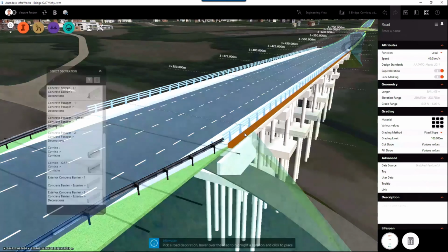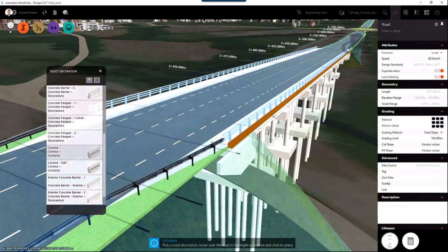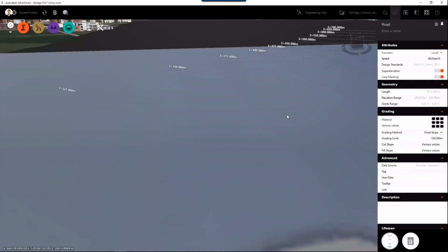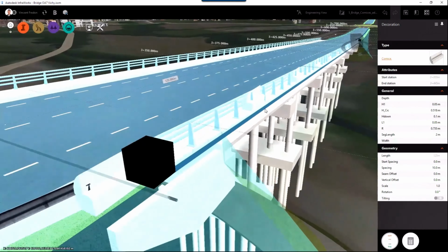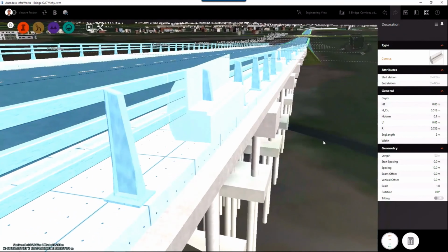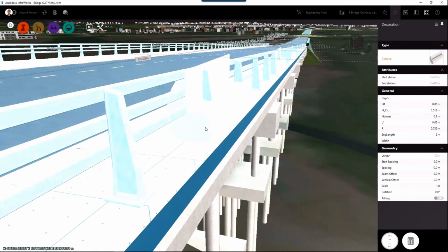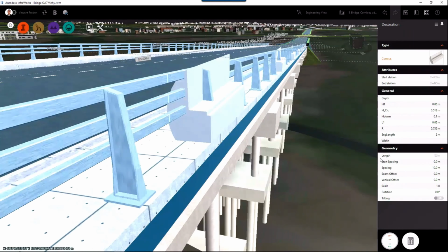We use a 3D parametric model created in Inventor and added to the InfraWorks library. The first positioning is this model. Then I use the parameters to modify the position, the rotation, and the elevation of this object because, of course, it's not at the right place. This is in the palette on the right.